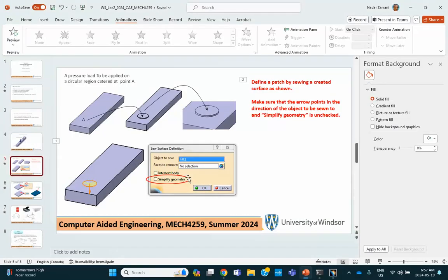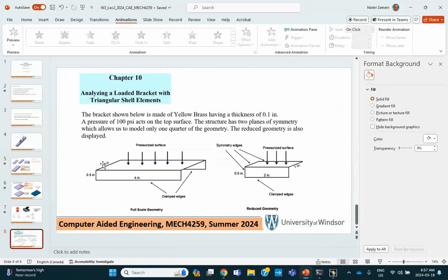So here's the situation. This is a thin structure. The dimensions are given, some dimensions here, and it says the thickness is 0.1. So immediately you have to realize that if this problem is to be solved with finite elements, you will have to solve it with shell elements. Okay? If you just do solid elements because you don't know shells or you didn't realize that, I'm sorry, but there's going to be a substantial number of point deductions.